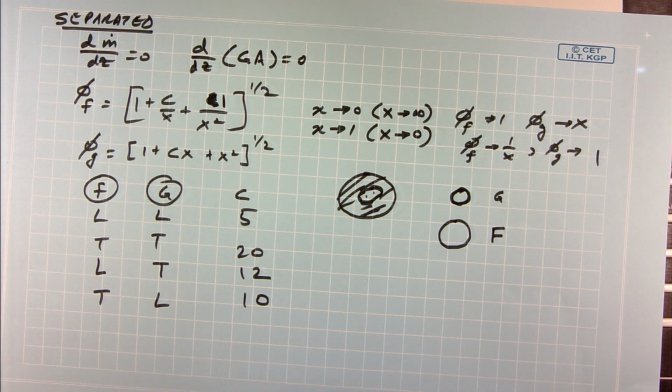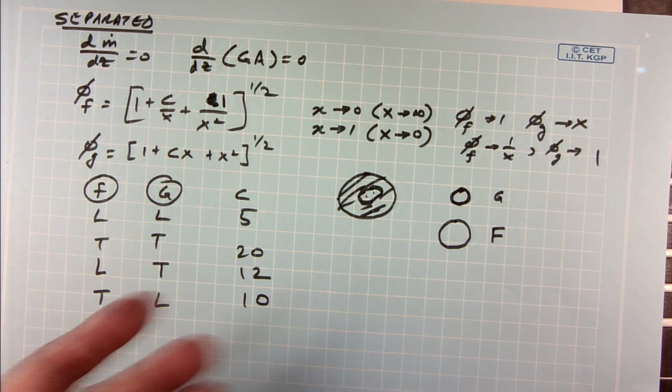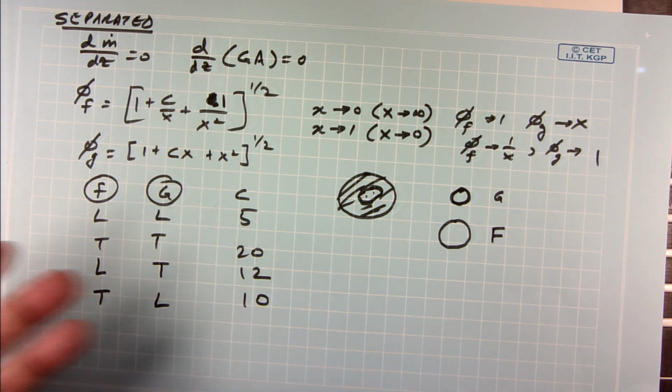In a homogeneous flow model, both phases are traveling at the same velocity. Okay. In separated flow model, each of them are traveling with two different velocities, but at the end of the day the pressure drop going from inlet to outlet should be the same for both. So, if I impose this condition on the separated flow model, I can go back and solve that complicated equation. Does that make sense? That is a general philosophy behind a separated flow model calculation.